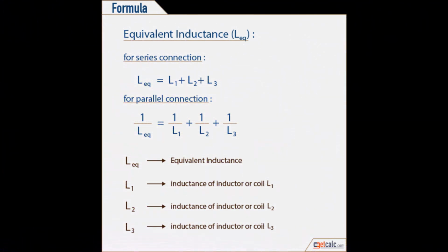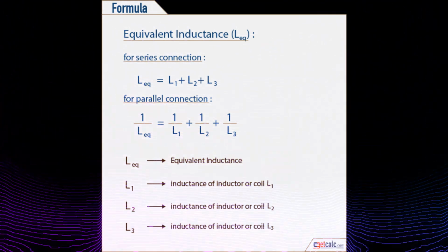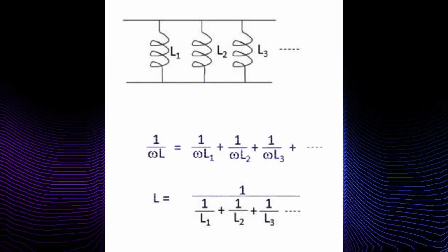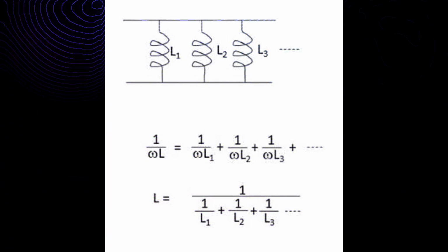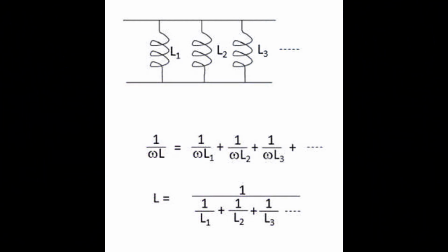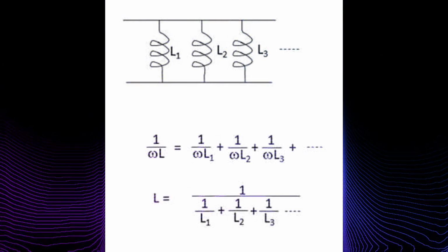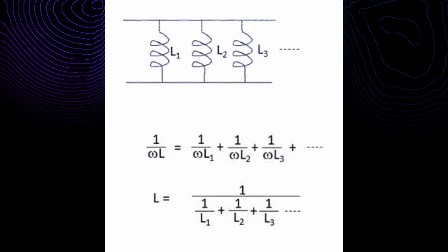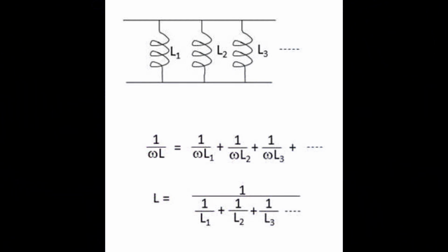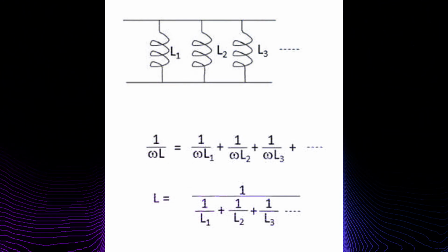To compute the value of impedance for the coil, the inductive reactance and resistance must be added. Since these two components form the legs of the right triangle and the impedance forms the hypotenuse, the Pythagorean theorem discussed before can be used to compute the value of impedance. Z equals the square root of R squared plus XL squared.